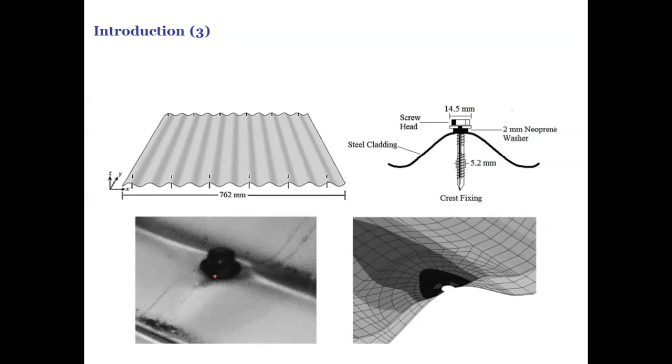So if this is the case, what we can typically do for the structural damage prognosis task is to monitor the crack propagation around this fastener. We can use the finite element method to simulate the crack propagation based on fracture mechanics knowledge. This is what people typically do in this scenario.